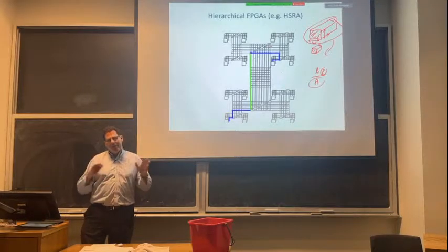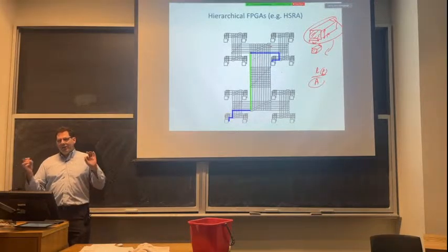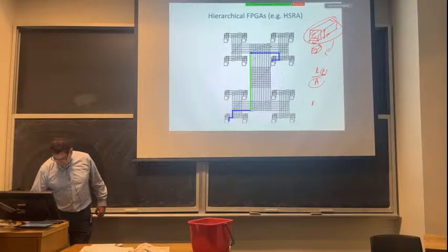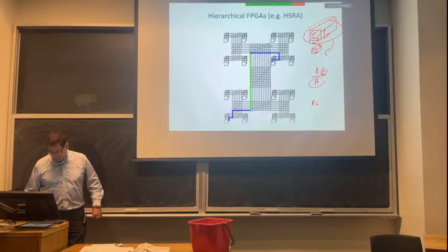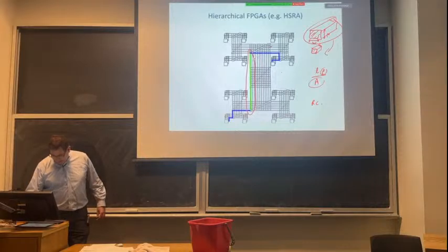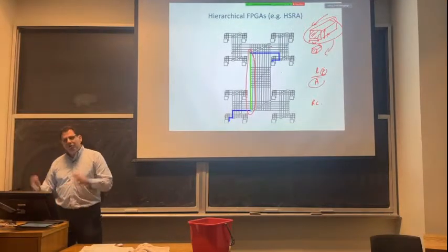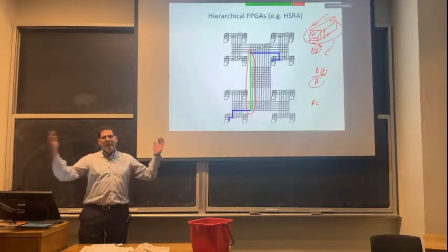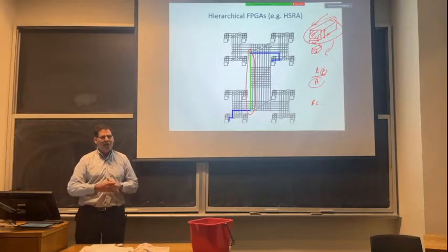And then if we go look at capacitance, it turns out that capacitance per unit length also goes down, so that's good, because your delay is actually proportional to R times C. So your capacitance per unit length goes down. For wires like this, I don't get the benefit of this length getting smaller. Wires that just cross the whole chip. If I make a new chip in a new processing technology, I just make twice as many logic elements. So I add another level of hierarchy. The top level of the hierarchy still crosses the whole chip.